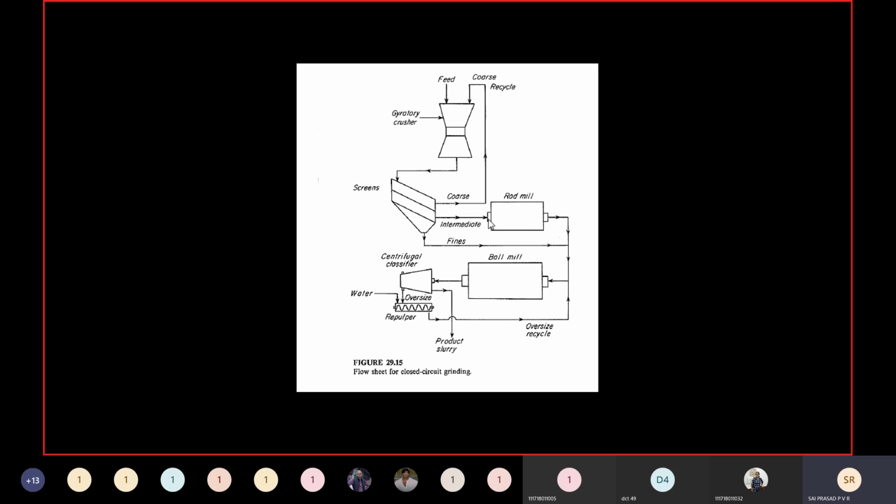See the diagram of a rod mill, the cylindrical part is longer, since it will be carrying a grinding medium of rods. And in the rod mill, how does the size reduction take place? When the rods roll over one another, size reduction takes place. Here we need not lift the rods to greater heights and allow them to fall. It is not possible, because of the robust construction of the rods and the power consumption would increase tremendously. So the rods will be rolling over one another. If the compressive strength of the material is less, instead of rods we can replace them with a tube mill. That is the only difference between the tube mill and the rod mill. The shell is the same, but the grinding mediums are different.